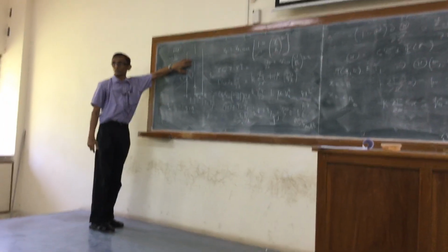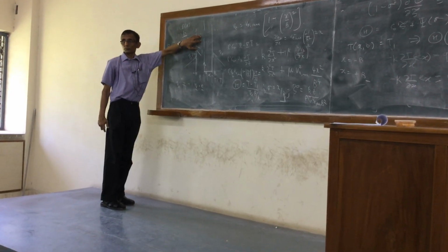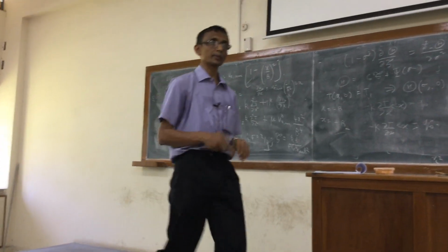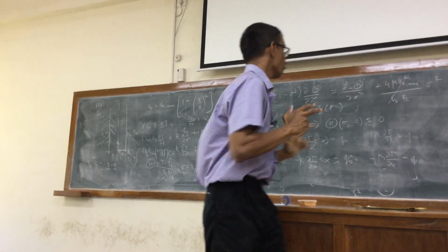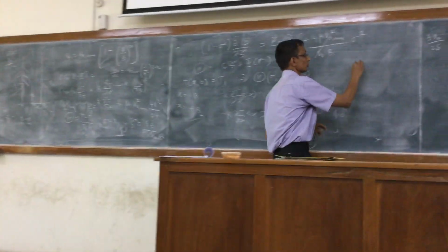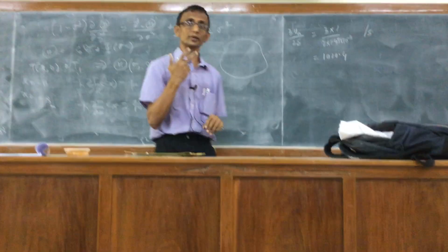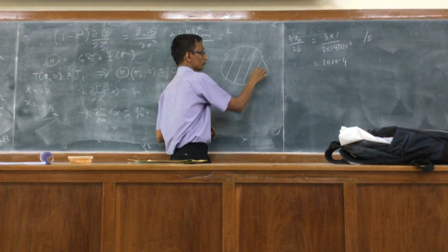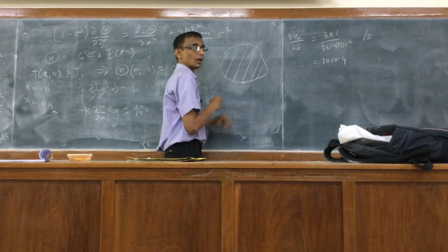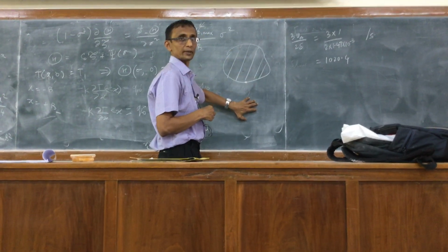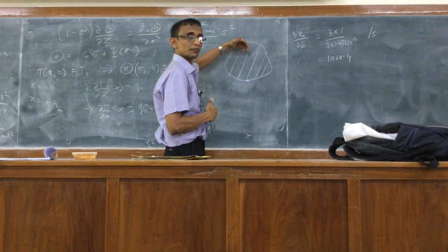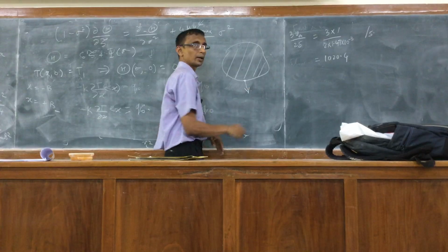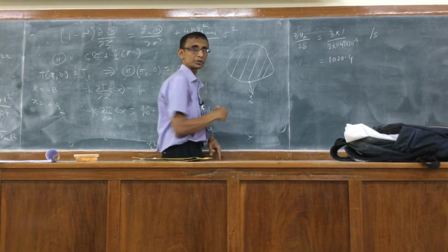At x equal to minus b, n is the outward normal. How do you determine what is outward? You have to know the convention again. If you look at a boundary, you encountered this with forces also. When we say the outward normal, I am focusing on the body, when force is transmitted to the body from the outside. Then the outward normal is coming from the body into the outer region. That is what we call the outer normal, n, for transmission of forces.